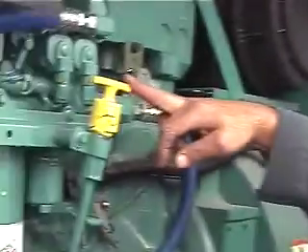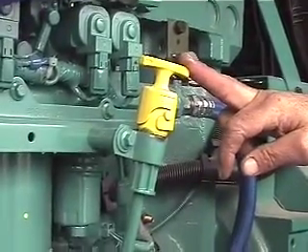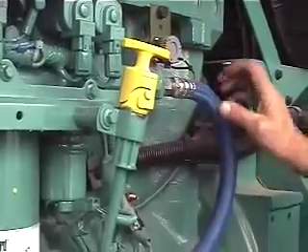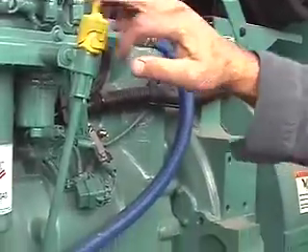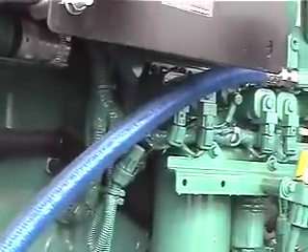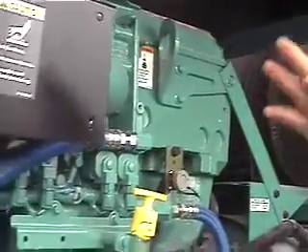You have an oil check here. It's yellow, so you can see it pretty easy. This is your fuel inlet line. This is a fuel return line. Fuel return comes out of the engine, goes up, and you'll see this unit has 3 radiators in it. It has a fuel cooling radiator, an engine cooling radiator, and an air cooling radiator. This one here is the one that goes through the fuel cooling radiator. It's kind of hard to see, but if you look up in here when you get a sec, you can see it.